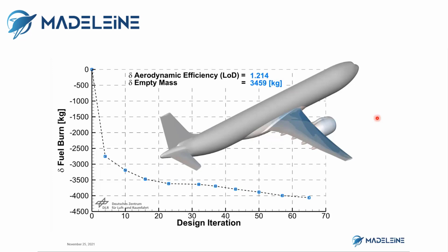For the XRF1 flexible wing shape optimization, is a constraint for span-wise lift distribution included? No. In fact, here there is no span-wise lift constraint for the pure aeroelastic optimization. On the contrary, for the MDO made by DLR, this is tackled directly by the MDO formulation, but there is no explicit center of lift constraint. But this could be added if needed.